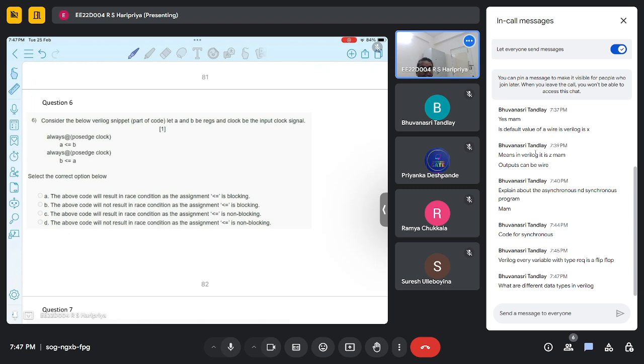Otherwise, everything in Verilog is going to be in binary, so it will be in the register or wire. All the processing will be happening in binary, and any negative numbers will be in 2's complement form.